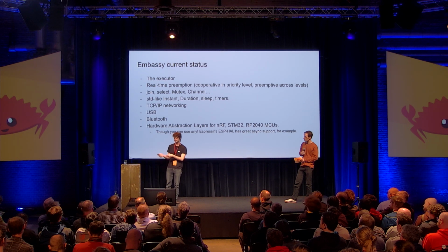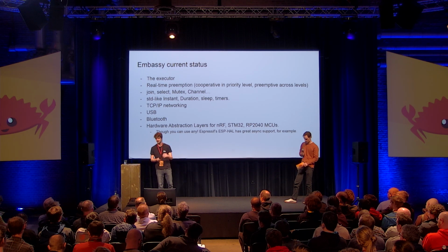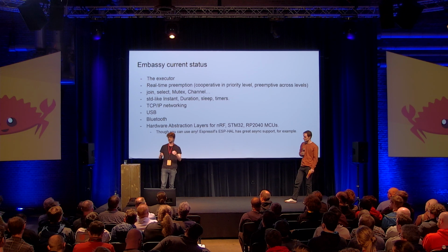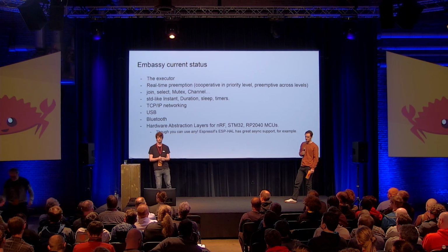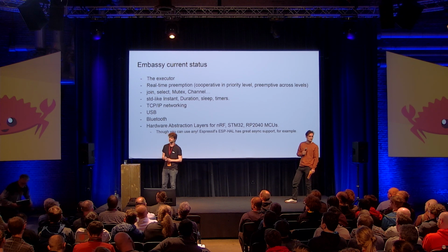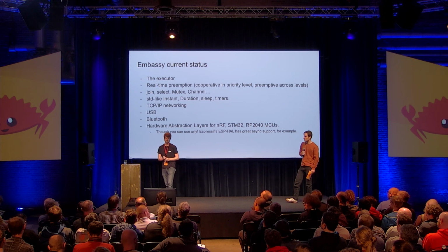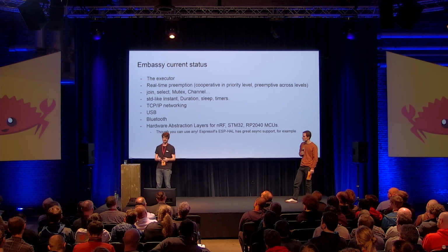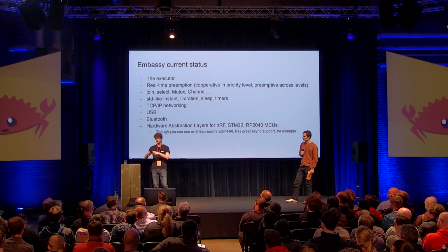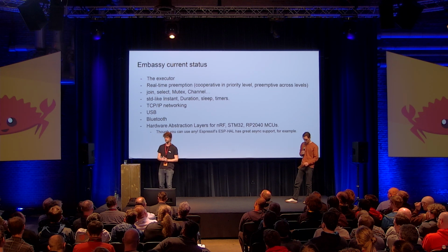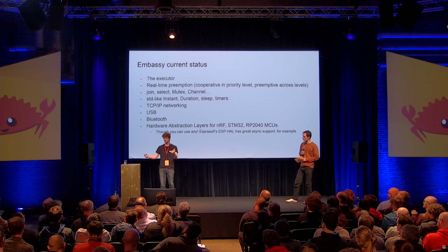You pay a bit of latency for the executor at the higher priority, but it's mostly constant time unless you do really egregious things. So yes, you can do real-time stuff with it. If you really cannot pay the overhead, you can of course choose to use raw interrupts, and you can even mix in the same program raw interrupts and async for the lower priority things.